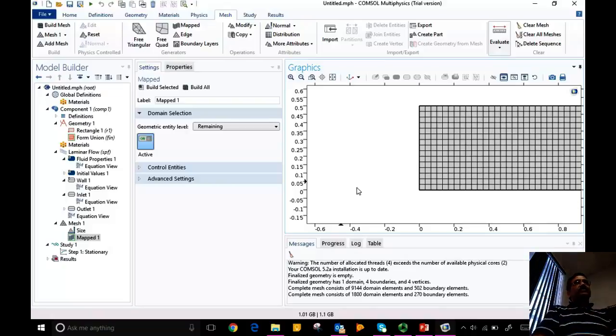I don't know the answer to that question. Why 2 cells? Why not 3 cells? Right. So that's driven by algorithm. But why it is a mapped mesh near the boundary is understandable because there is a boundary layer there. Okay. So my question is, so the model is already assuming that we are solving an equation such that there will be a boundary layer already there before making the mesh itself. Right, right. So those are the only 2 pieces of information they have.